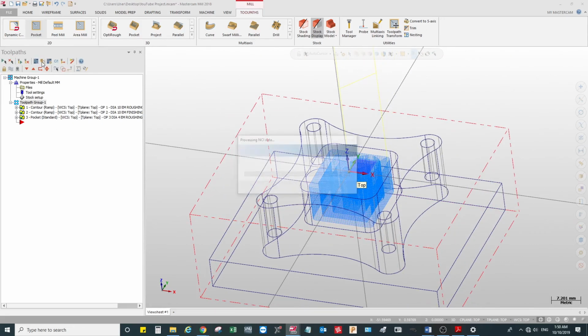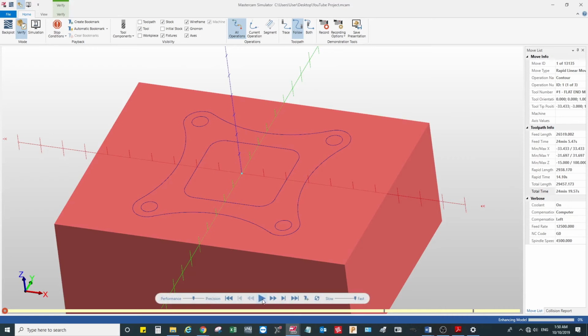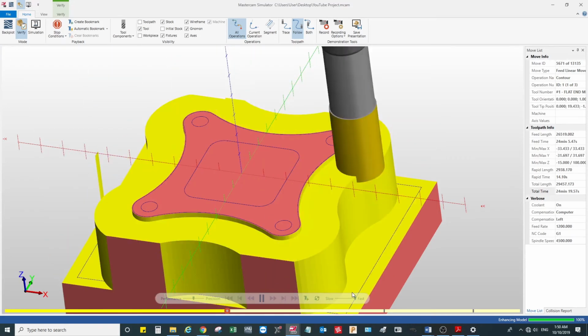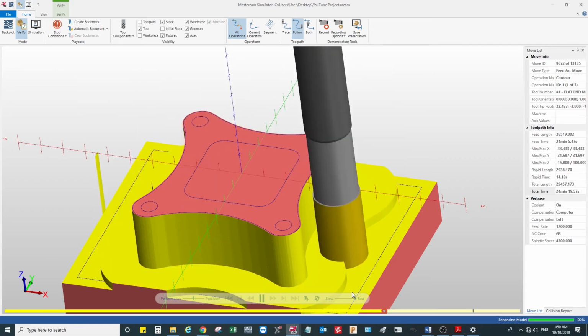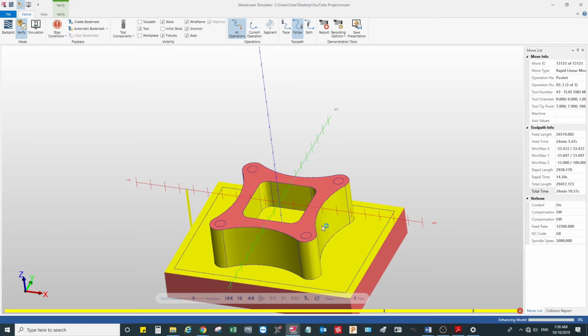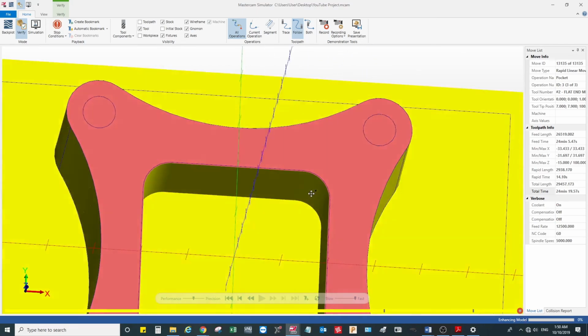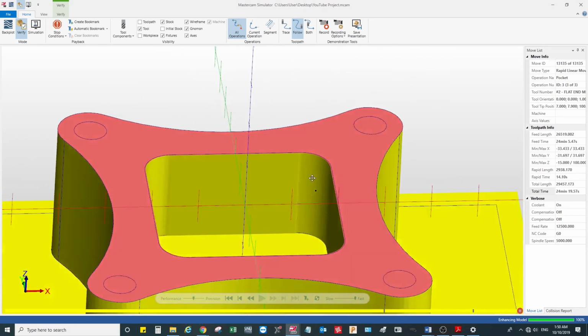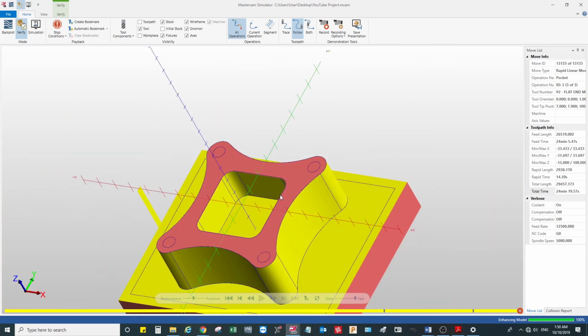It would be the second tool number, and then I'm going to make some modification to the feed rate. I'm going to go a bit slow, 1200, and somewhere around 5000 RPM. The plunge rate is really high, so I'm going to go with 800.